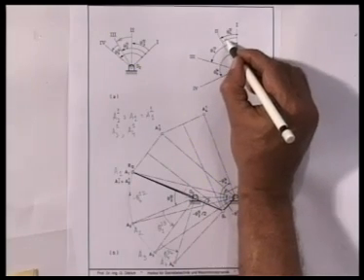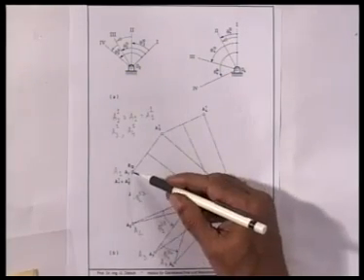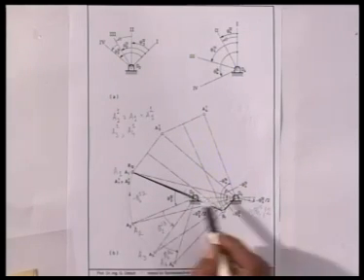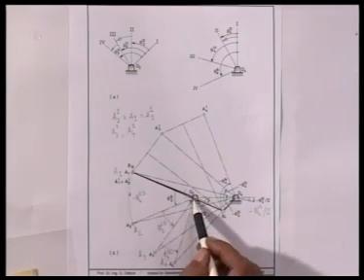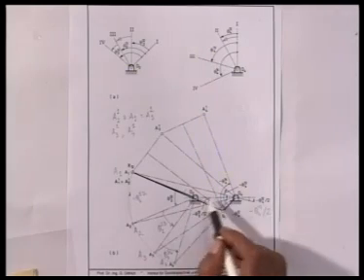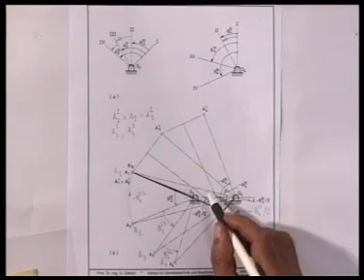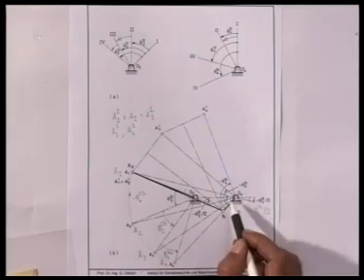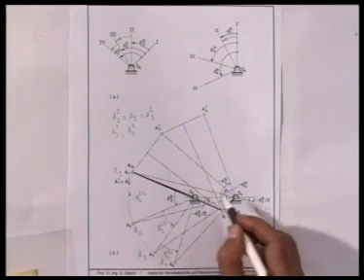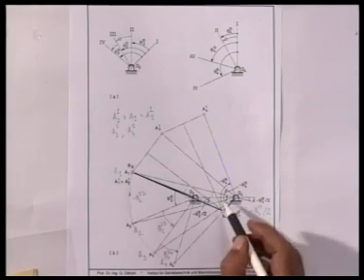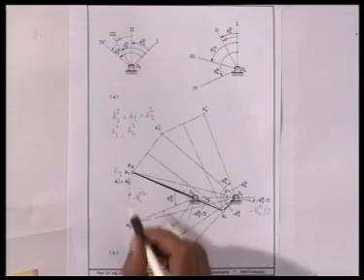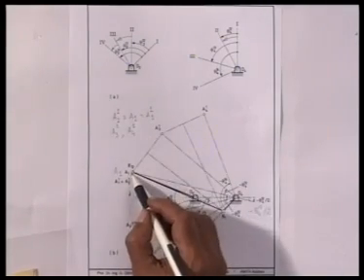This is theta 4 1 2, which is counterclockwise. So, I rotate it clockwise, and because O4 A2 equals O4 A1 and O2 A2 equals O2 A1, this becomes an isosceles triangle. O2 O4 becomes the angular bisector of both of these isosceles triangles, and because this angle is minus theta 4 1 2 by 2, the total angle is theta 4 1 2. Thus, A21 has coincided with A11.